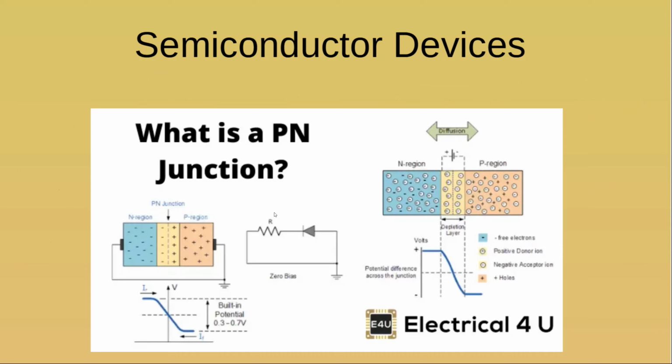So when you look at the structure for a p-n junction, you can see the junction here, and this becomes the depletion region, which is shown better over here. And you get this electric field across it, which is the potential that you have to offset when you bias the junction. It will not conduct until you get up to that threshold voltage. And then it will conduct electrons from the N to the P.